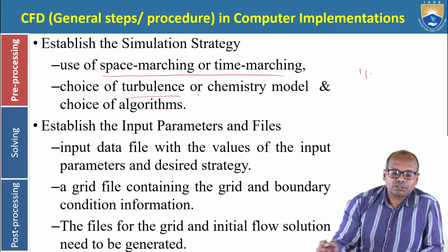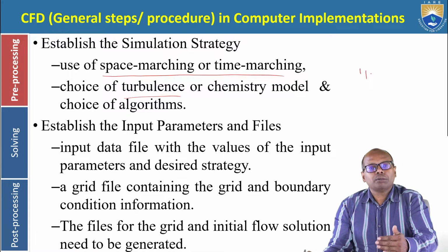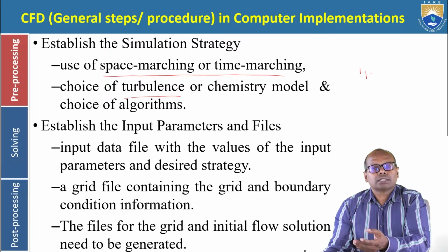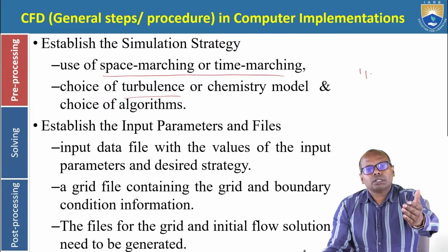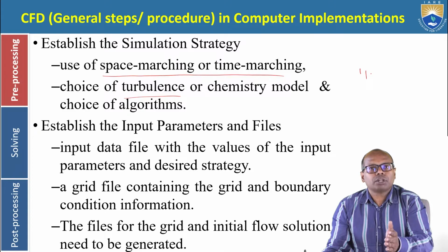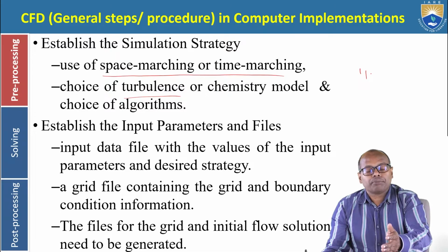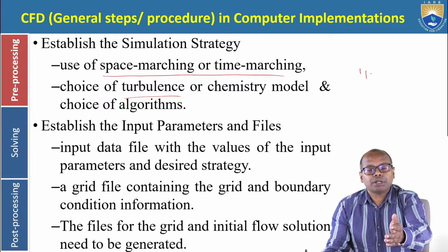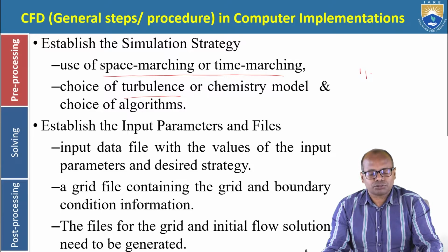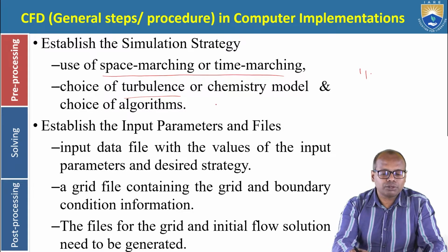And what is the turbulence model or chemistry model? There are many models like k epsilon, k omega, SST, and we also have large eddy simulation, LES. Like that we have many models. So which type of turbulence model we are going to use? If temperature is involved, we have to consider the energy also. Like that, what type of model we have to specify, that also we have to do.